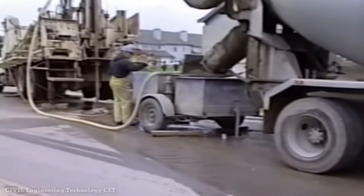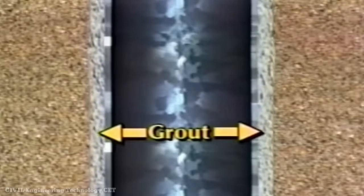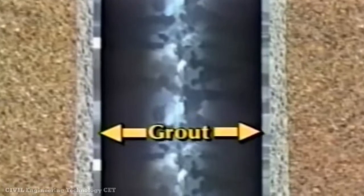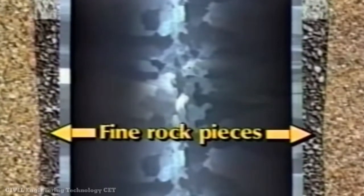The space between the drilled hole and the casing has to be filled to prevent surface water from migrating downward along the outside of the casing and contaminating the aquifer. This filling is called grout, and it may be either cement or a special clay called bentonite. Sometimes, most of the space is filled with fine rock pieces from drilling, and then the top 20 feet is grouted with cement or bentonite.